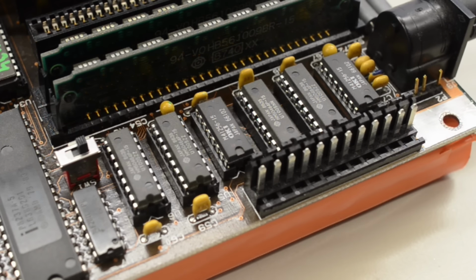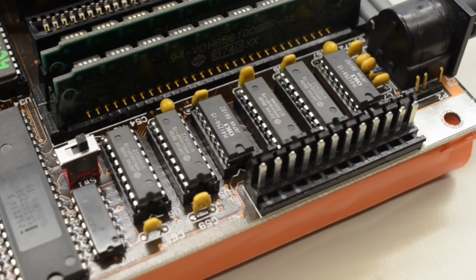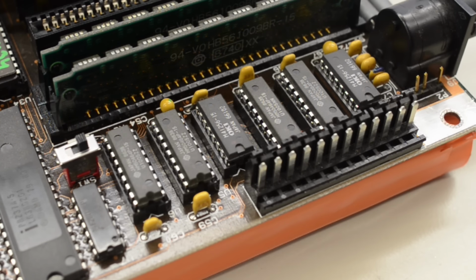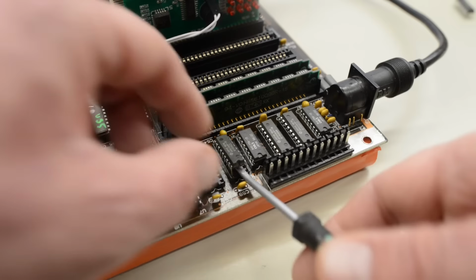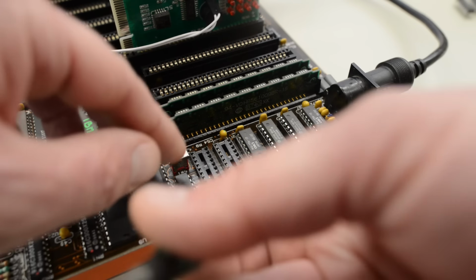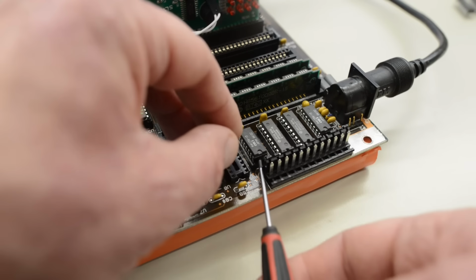Okay, next we have these onboard RAM chips. So these are 512K to 640K. They are disabled with jumper J10, and they are not needed to post. And this is not where the error is pointing to. But I don't know exactly how that test works. So let's remove them and see if that makes a difference. So this too is highly unlikely to be causing our issue, but very easy to eliminate. So let's remove them anyways.